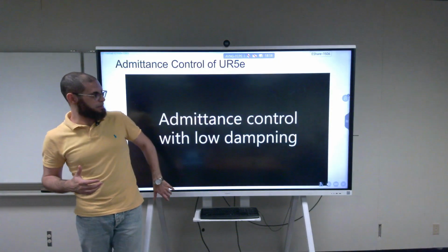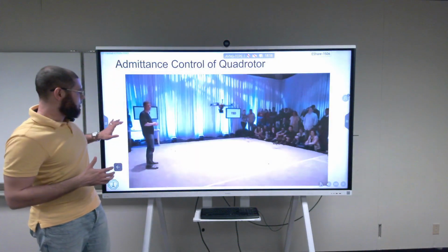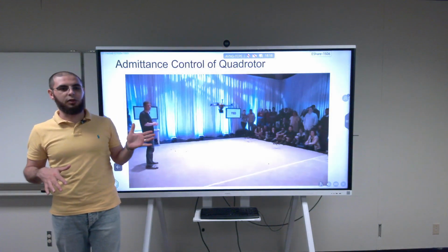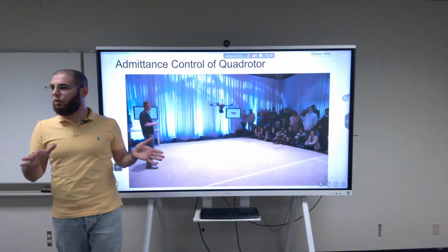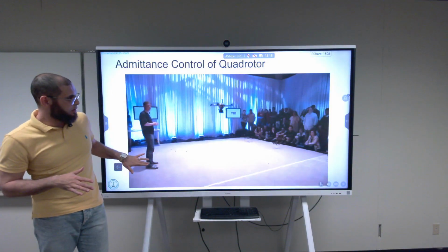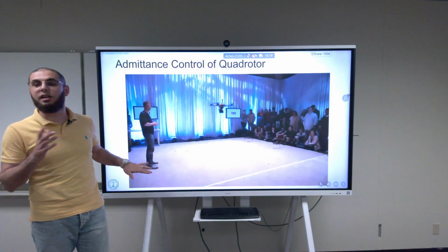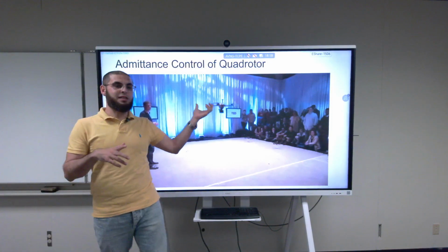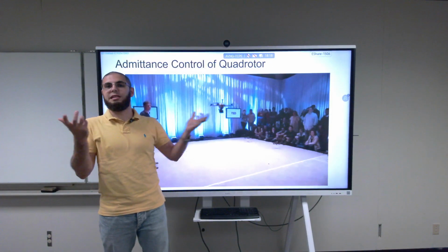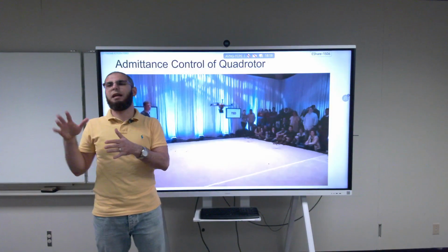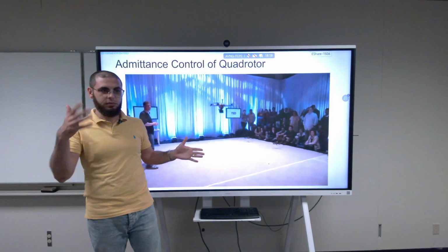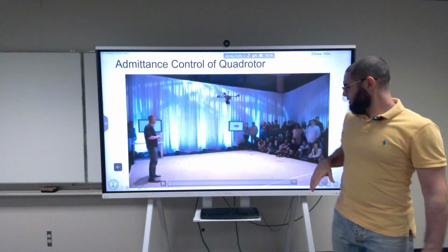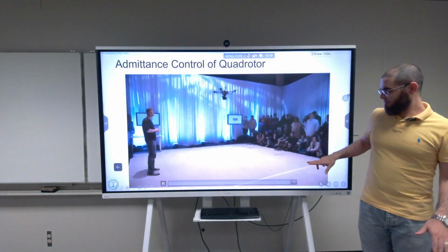Which brings us to the last part, doing it actually with drones. Same idea with drones. This is the group of Raffaello D'Andrea, again one of the top in the field. And this is one of his TED Talks where he does admittance control for a quadrotor. They don't have a force and torque sensor on the quadrotor, so the way they do it is that they estimate the force using some Kalman filtering and stuff like that. So that's another way you can do it. This is actually a very nice video, and that's the last video of the course.